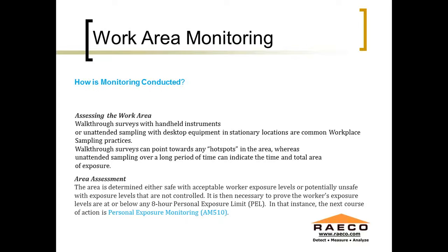Area assessments, this is another common area. We work with Detroit DTE Energy, and what they do, they use real-time photometers to measure around their coal conveyors, and what they do is to justify the type of dust suppression equipment they have in place. For instance, they did a study where they had vacuum-style dust collectors that they did not feel were very adequately removing dust. They wanted to move towards a misting type machine. Basically, the mist agglomerates with the coal dust, settles down onto the ground.